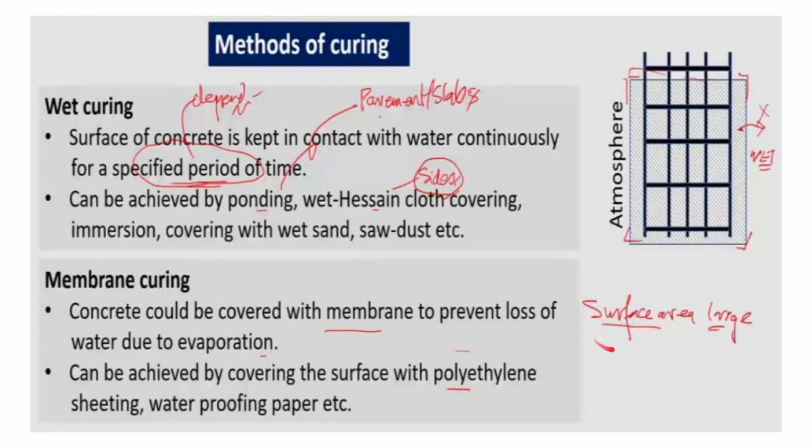But when the surface area is very large, for example in flat road conditions, it may not be possible to completely perform wet curing, or if the structure is not horizontal and is inclined, it may be difficult. So in that case membrane curing is used.